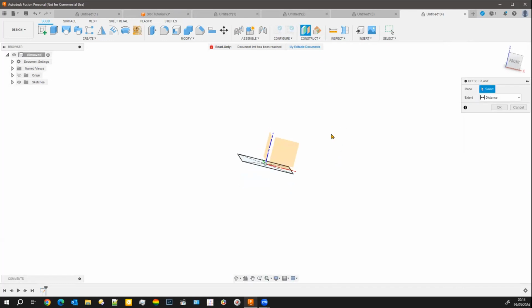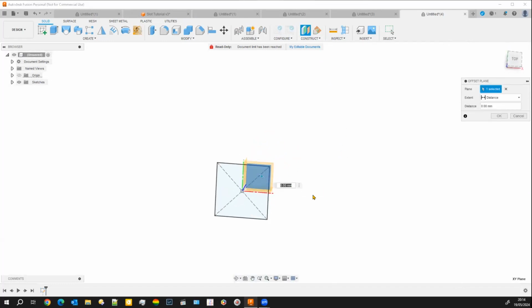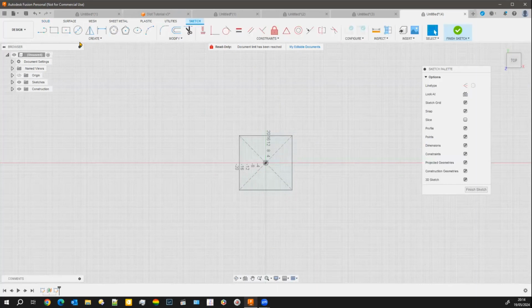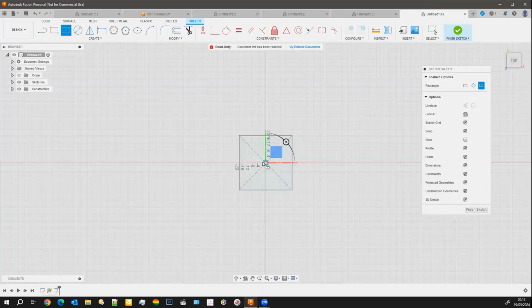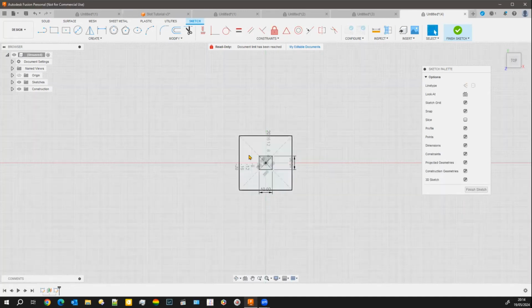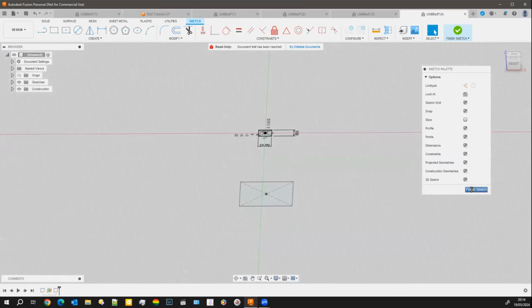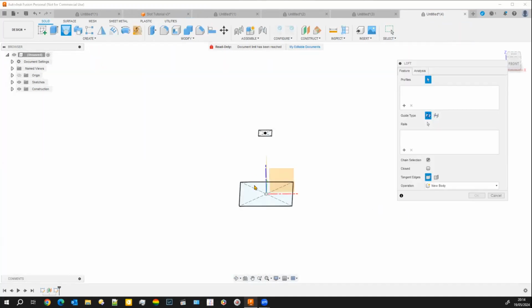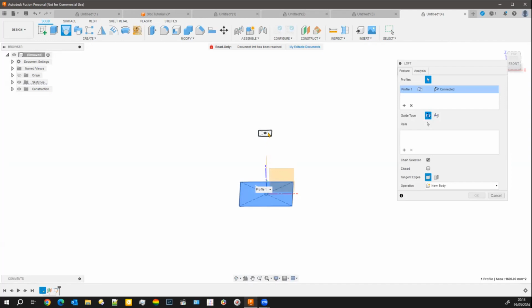Let's get the right plane there, and we'll go up 50 mil. And then on that plane, on the center, do a 10 by 10 rectangle. Now, if you loft that, you'll get straight lines. Well, yes, of course you will.